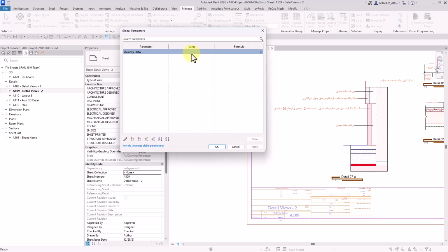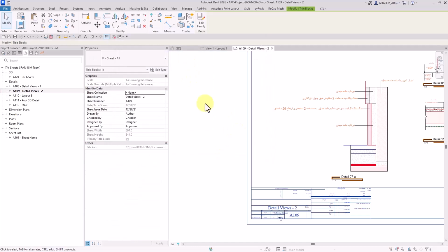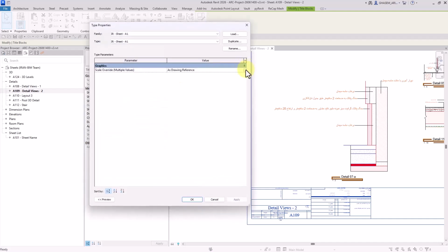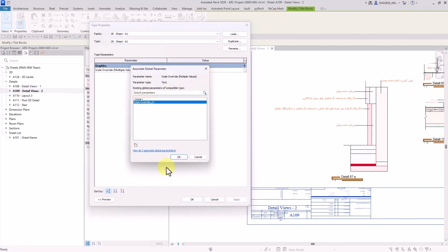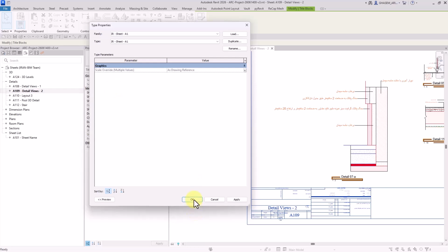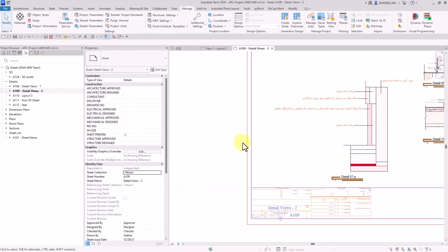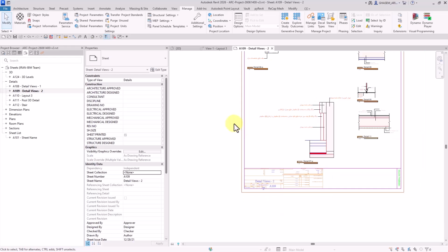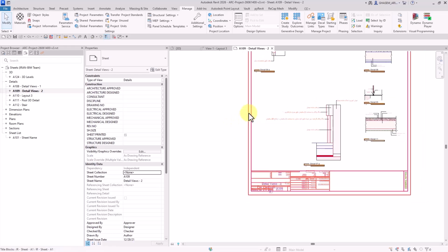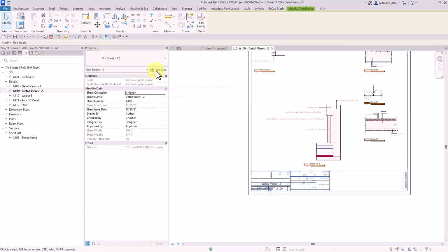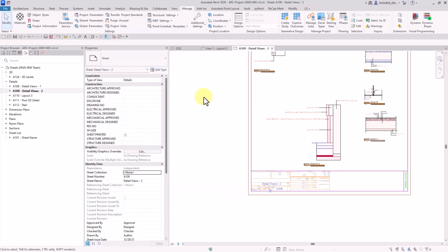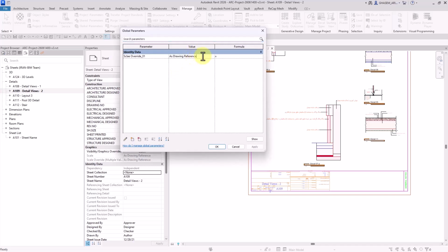Right. This will do. After creating the parameter, we can specify a value for it. I'm going to go with the same thing as before. And after that, we can select this parameter here. Let me set it for this bar. Now guys, as I said, we might be using such parameters for different purposes, like for example, in different title blocks. In this case, we don't really need to edit the title block separately from here. If we are sure that we want the same value for all of them, we can just modify this parameter.